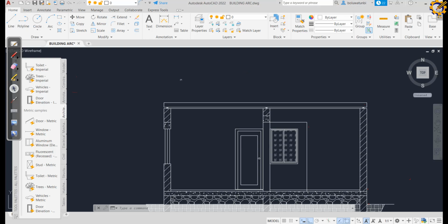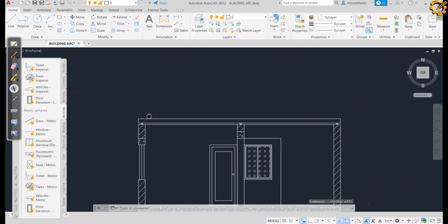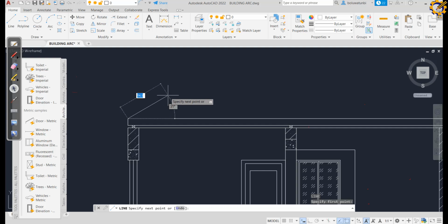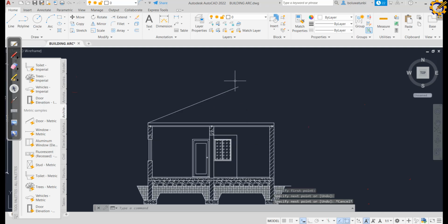So I'm going to pick my line, switching off my auto mode. Pressing tab, 23, tab again. So already logged in at 23 degrees like that. I'm going to draw towards this axis like this. Check.